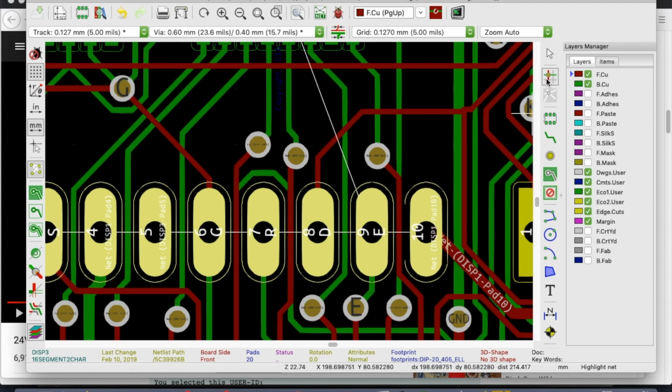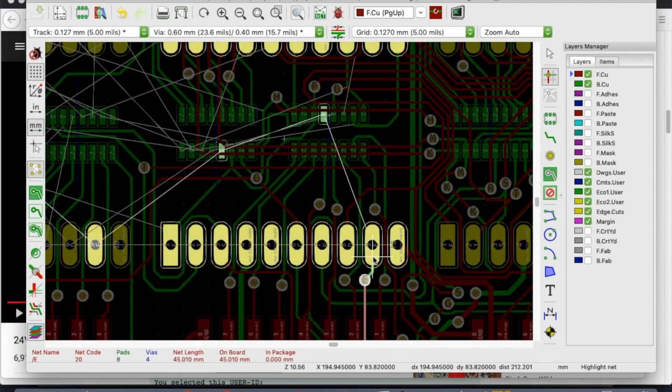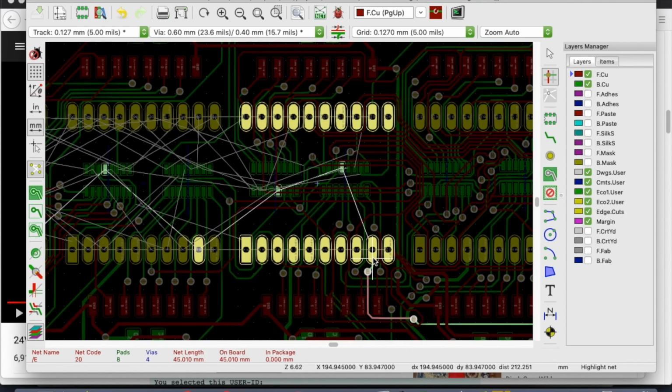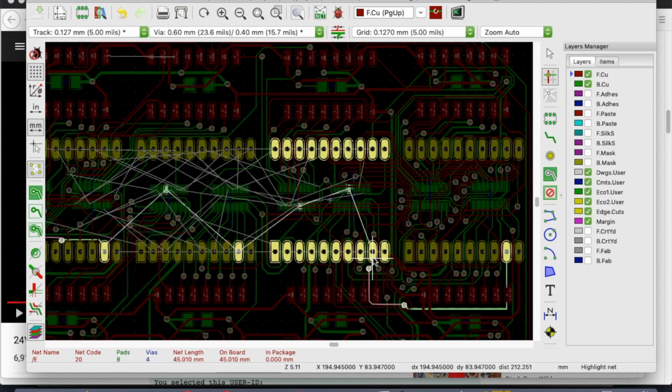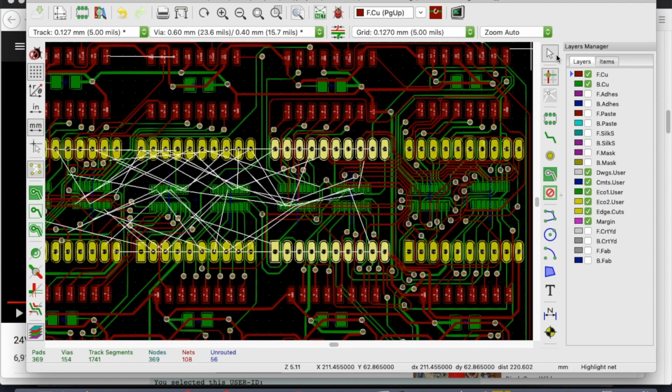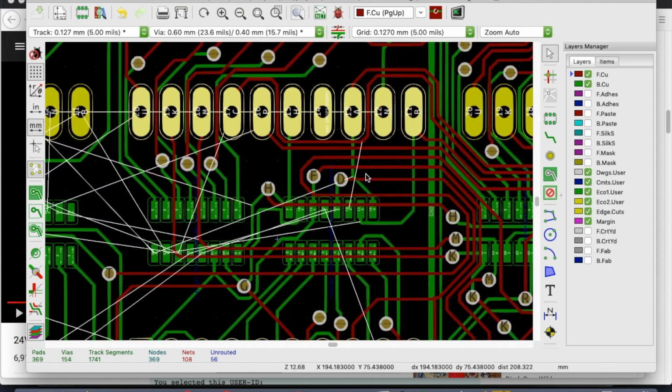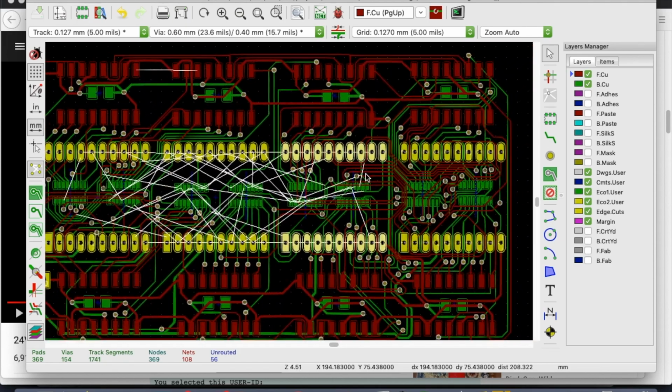So one tool we can look at, before I forget, is the View Net tool. So if we click on that and zoom out, you can see everything that needs to be connected on this net. So we're going to make this connection from here to here, but there's still several more links to go. So we're not out of the water yet. Okay, get the contrast back. Alright, let's see. Half the challenge here is just not losing your place.